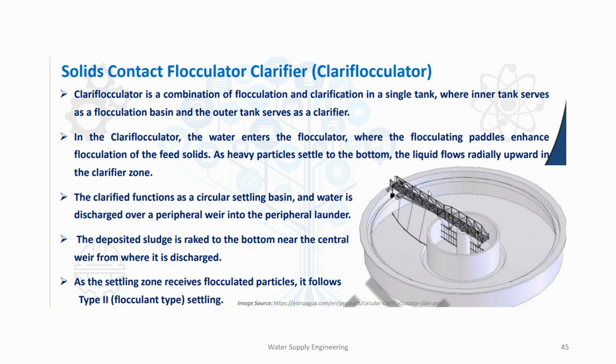The figure shows a clariflocculator, that is a solids contact flocculator clarifier. In the clariflocculator, the water enters the flocculator, the inner chamber, and there flocculation or floc formation happens, as we saw earlier in a question. Destabilized particles join together and form flocs, and these heavier particles settle to the bottom and the liquid flows upward in the outer clarifier zone.